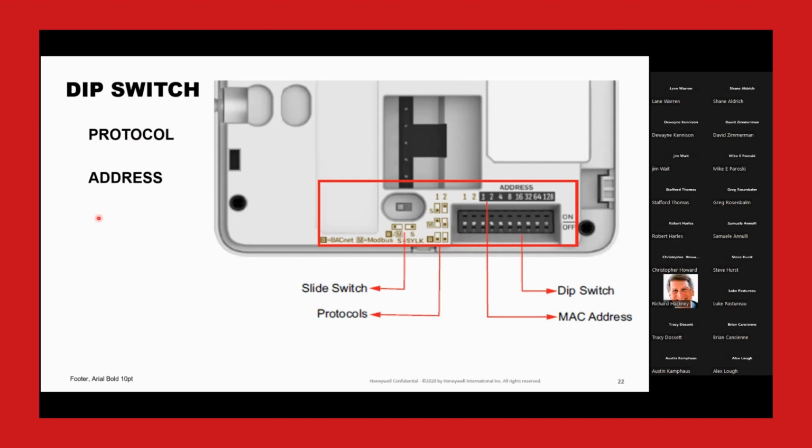I've brought in a fully loaded Honeywell VFD and a fully loaded IQ sensor. The Honeywell Spyder 5 didn't even break a sweat. So I'm thinking it's more of a soft limit, not a hard limit. And just to show you how the configuration is done, you throw the switch, depending whether you're doing 485 or Silk, and you use these 2 addresses here, 1 and 2, to set it for Silk, Modbus, or BACnet. So this is the electrical switch, and 1 and 2 is the protocol switch, and then you've got the MAC address here as needed. Excuse me.